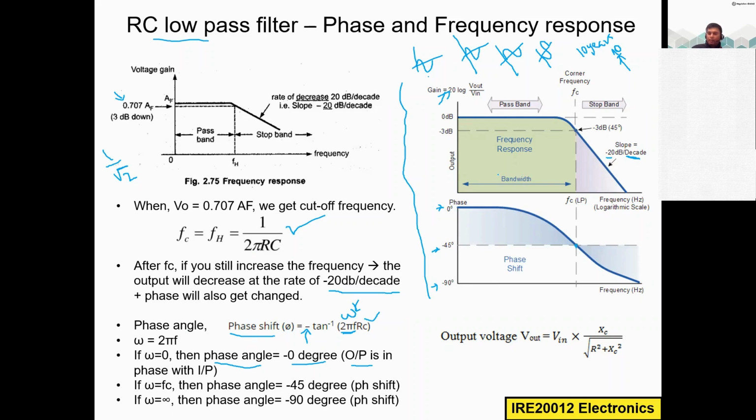Here you can see a pass band and stop band. I told you whichever filter it is, it passes certain frequencies, that is called the pass band, and it stops certain frequencies; that region is called the stop band. We can calculate the FC cutoff frequency value using the formula 1 divided by 2 pi RC. If I calculate the cutoff frequency for this filter, maybe it is 50 kilohertz, or 25 kilohertz. It passes the signal and then starts to fall down at the cutoff frequency value.